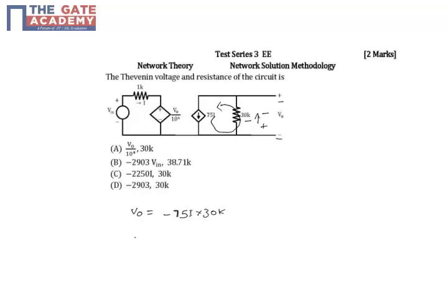Now I will be determined from this particular loop. So this current is what I is. For I, the equation will be V in minus this divided by this. So it is V in minus V0 divided by 10 power 4 divided by the resistance, which is 1 kilo ohm. Now, simplifying this, we are substituting this particular value of I into this equation.